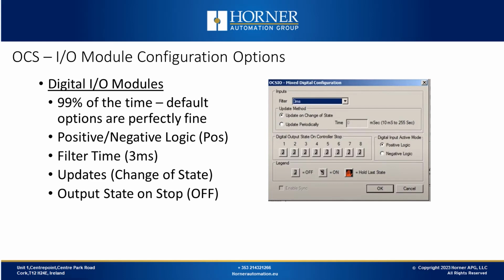Now the one thing you might change occasionally would be if you ever need to configure the I/O points for negative logic instead of positive logic. Then you would go into the configuration for that particular module and change the input configuration from positive logic to negative logic, but that's the exception. 99% of other cases we just leave at default.